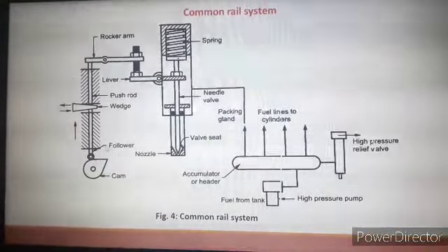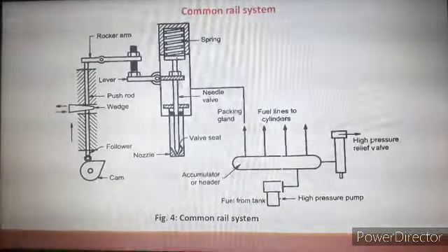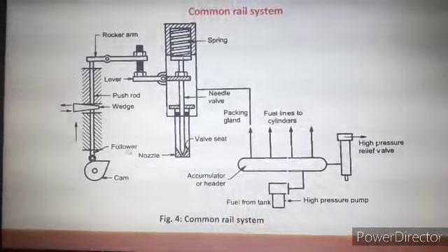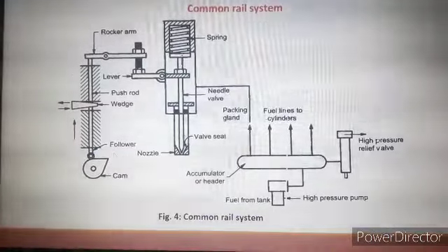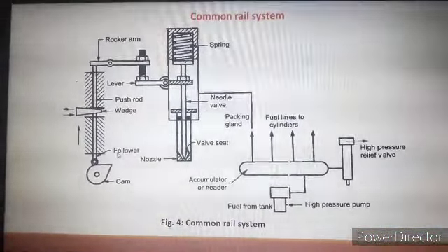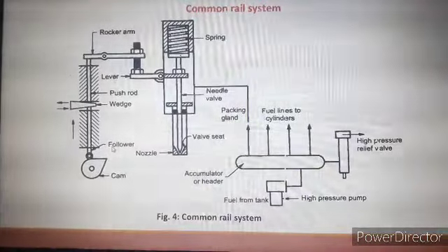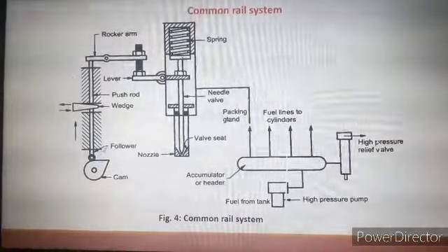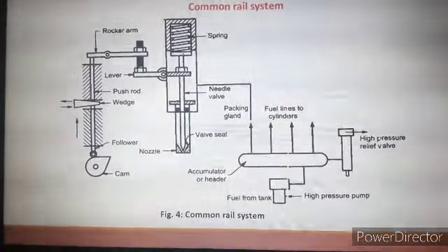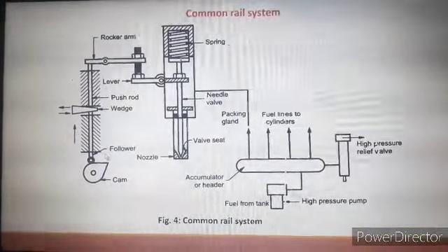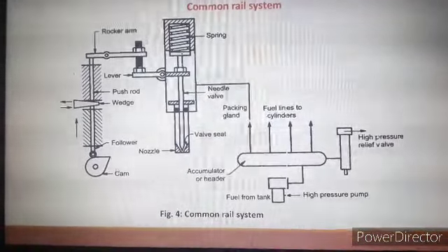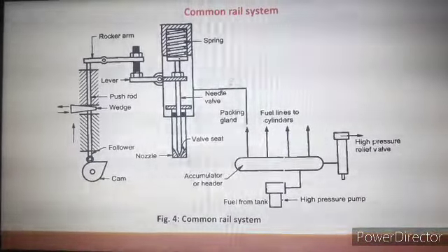These cams and followers are connected to our engine. Again, we know the different periods for the cam as well as for the follower. In case of cam and follower, we have the dwell period, rise period, again dwell period and fall period. So how are these periods defined? That is as per the working of our engine. We know that in our engine we have 4 different strokes, that is the suction stroke, compression stroke, power stroke, and exhaust stroke.